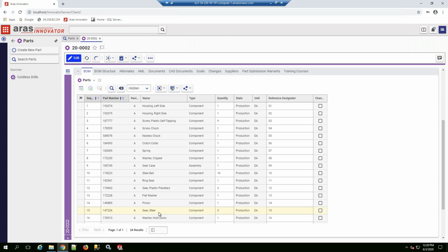Now, of course, the next time you change the parent, that gets fixed, but a lot of people don't like to see that. They don't like the fact that when they look at a bill of material, they see items in that bill of material that are the wrong revision, that there's a newer rev out there. And so we, through the change management suite, do what we call float. We float that new rev up to the where used of the previous rev part. So that's what we did here.